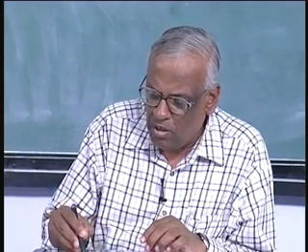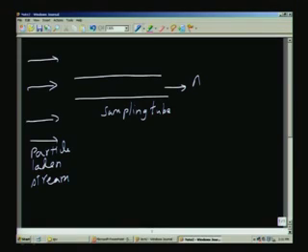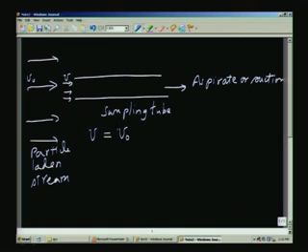I have to aspirate or suck it out by some suitable means. So, we have to have a suction device, that means you have to make sure that there is a pressure gradient available, so that the stream will enter this. What I want is for the stream to enter with the same velocity. This should be u, this is u naught, I want u equal to u naught, because that was the requirement.